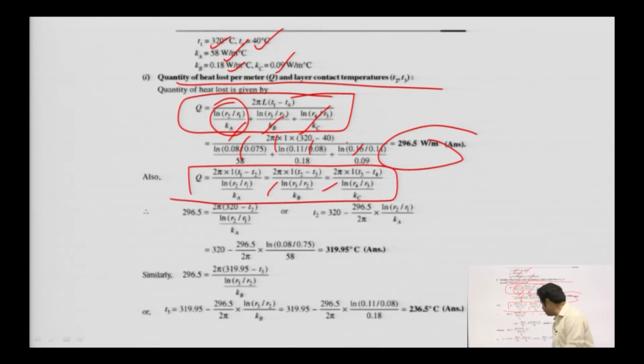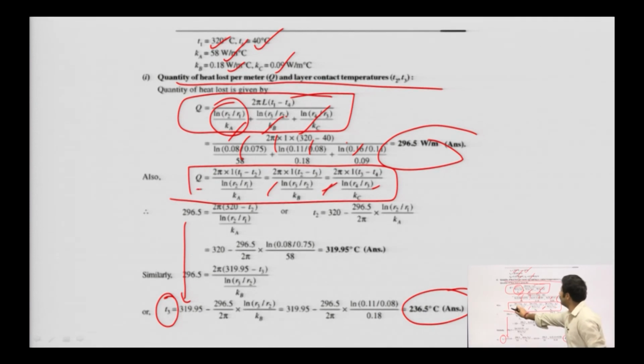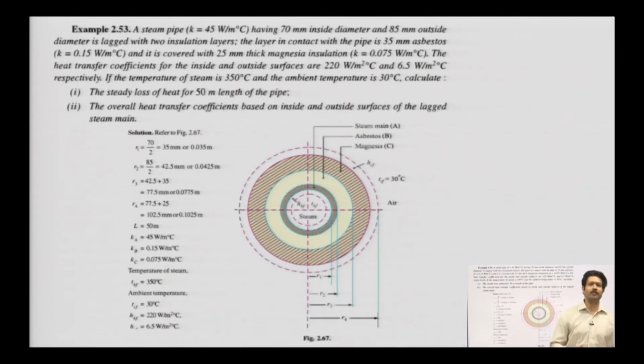So here also you will do the same thing, and with simple mathematics you can calculate the contact temperature. See, the same thing, the Q entering here is going out, so you just have to play with the contact resistances and the temperatures. See, the concept is same.